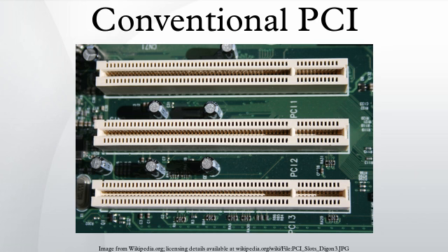All devices drive the signals high for 1 cycle before ceasing to drive the signals. Signal timing. All PCI bus signals are sampled on the rising edge of the clock.